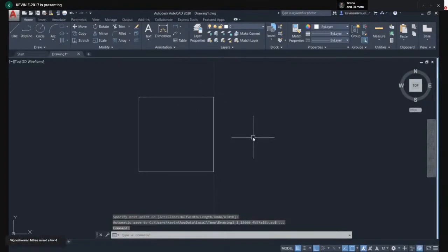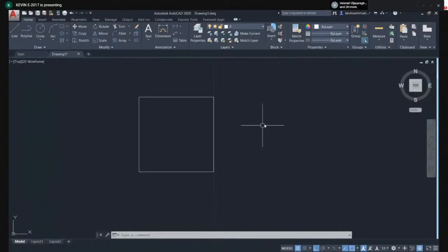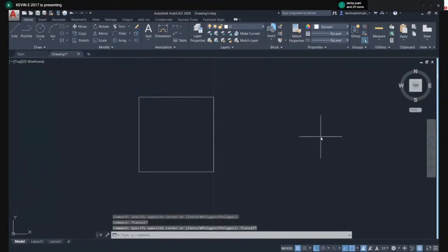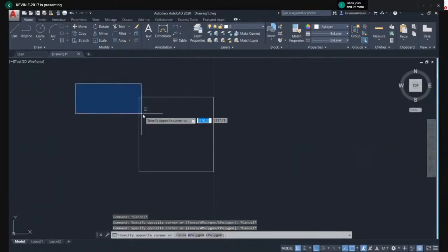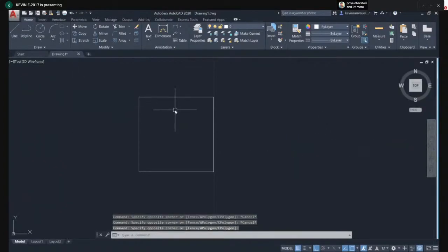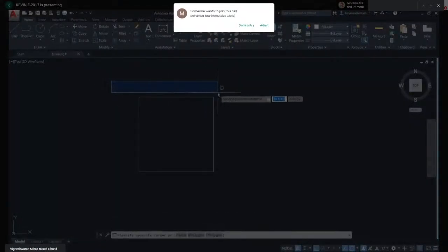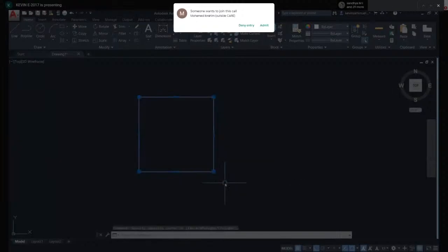And coming back to the selection, in which you can select a particular object, you can always use the left mouse button, and there will be a highlighted green area in which you can select it. And also you can select from left to right. So now here I am selecting from right to left and left to right. The difference is that when you select from left to right, you should always completely cover the object, and only then will the entire object get selected.